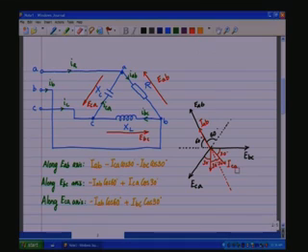That is, it is equivalent to saying now that we have values here in this fashion. So, we have root 3 I, this is I and this is I. So, this is equivalent to saying that we have in this direction root 3 I by 2 in the minus direction, plus ICA I cos 30, that is root 3 by 2 into I. And in this direction also we have the projection root 3 I by 2 getting projected here in the plus direction.